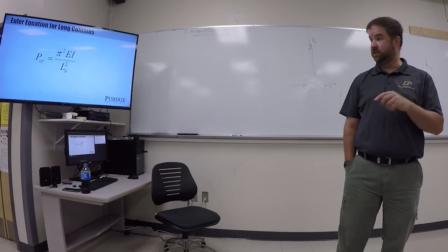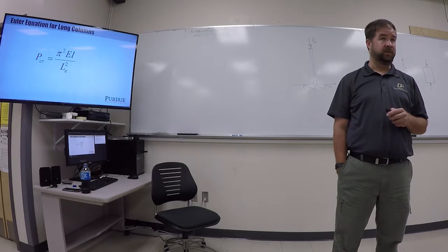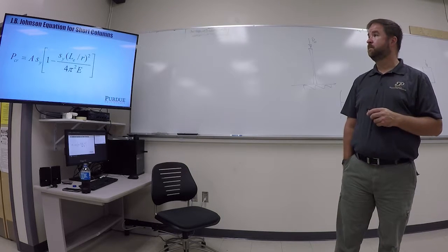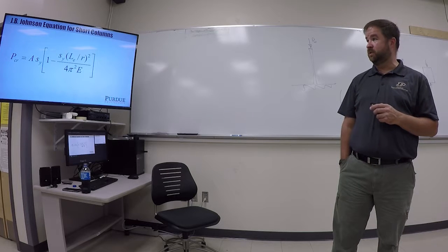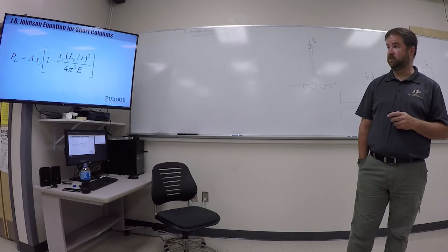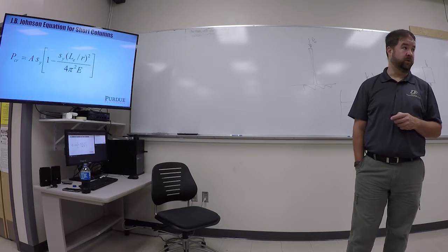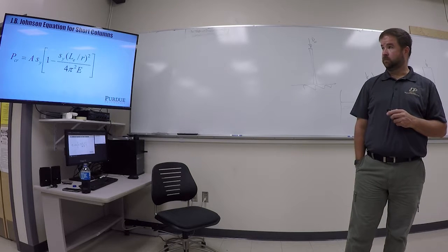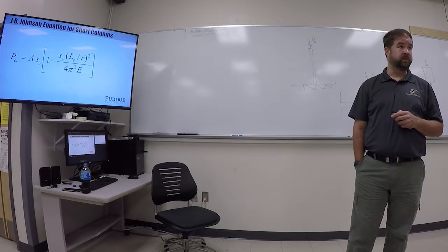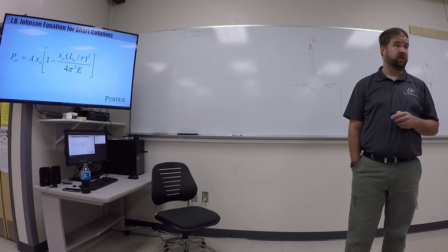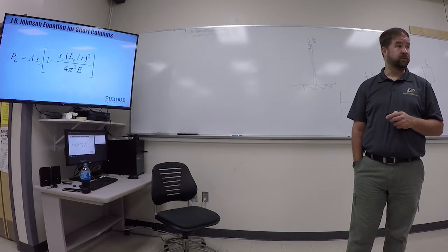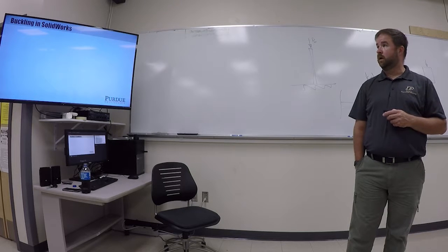So when we're doing the hand calculations, I'm giving you all the equations that you need in order to do some hand calculations for the assignment. J.B. Johnson is for short columns, a little more complicated mathematically, but the same factors play in there, and it also gives us a critical load that a short column can handle. With a short column, yielding of the material is going to be more important, as opposed to the longer columns, where stability is the concern because they're much longer.